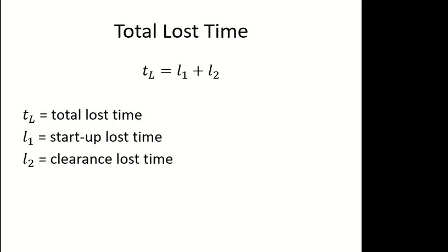So we were on the eastbound side, the signal became yellow and you thought, okay, I'm too far, I will stop now. So you stopped. So clearance loss time started. Now you stopped, the signal maybe has 0.5 seconds of yellow left, then we have the all red time and then the next signal will become green. So this half a second of yellow and the all red time is part of clearance loss time, and we represent it with L2.